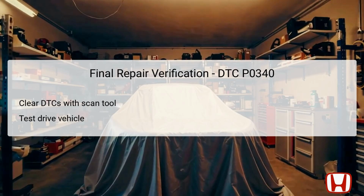The technician should monitor the vehicle for any reoccurrence of the DTC. Ensuring that the check engine light does not illuminate again confirms the successful remediation of the issue. If the DTC does recur, further diagnostics may be necessary, indicating that the original problem was not fully addressed, or there may be an underlying issue still present.